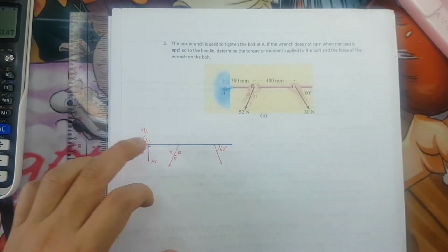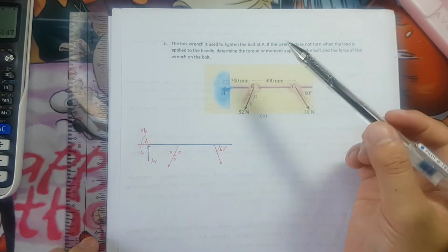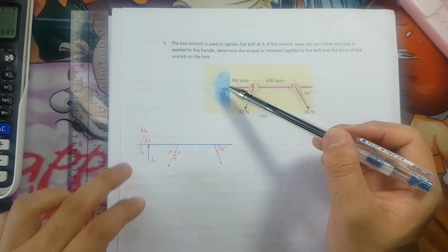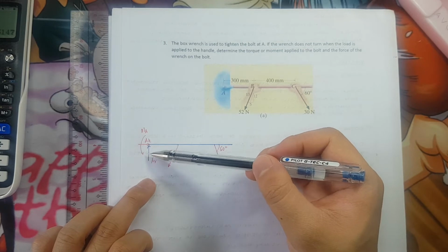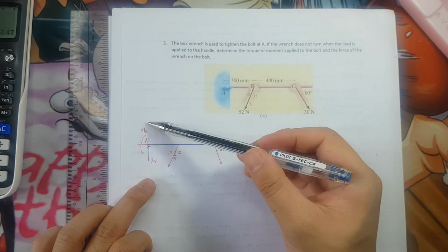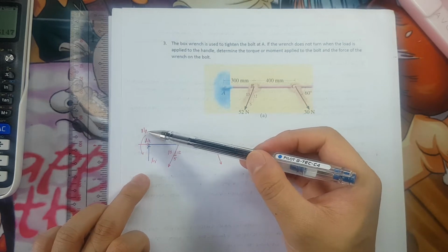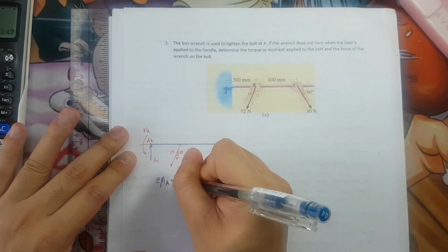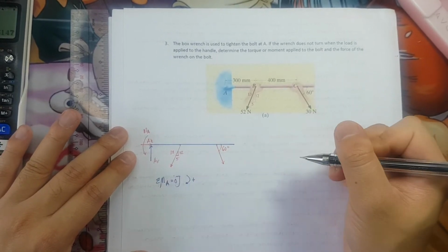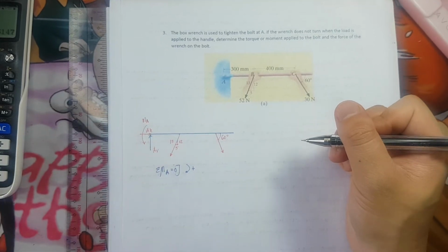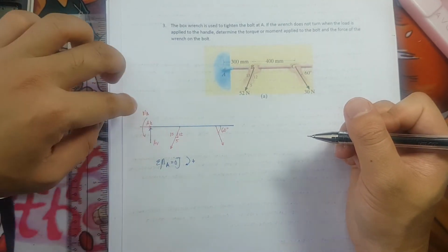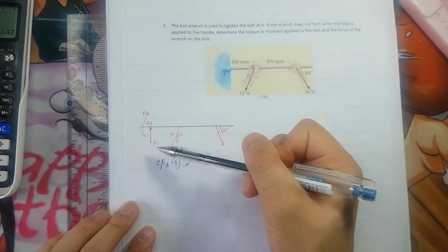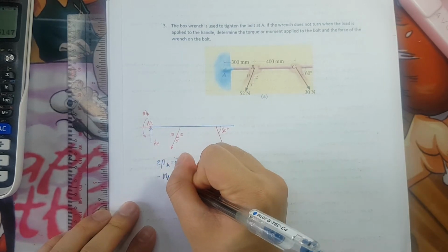the moment first, because since we already have one support, we can only have our moment at point A. So if we will be having our moment at A, we will cancel out a vertical and a horizontal. We can determine the moment A. Summation of moment with respect to A is equivalent to 0. All forces rotating clockwise should be positive. So what are the forces rotating? So we have MA. I assumed my moment A to be rotating counterclockwise. So that is negative moment A.